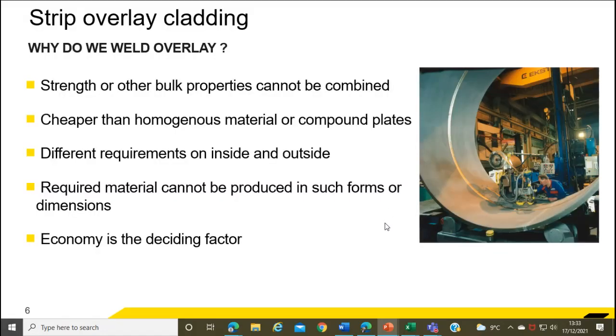So, making a start, introduction to weld overlay using strips. Why do people overlay in the first place? It's really because it would be too expensive to make a solid part or a whole item from the corrosion resistant material or the wear resistant material. It's very much cheaper to get the mechanical properties of carbon steel, high tensile, whatever, of a cheaper steel, and then coat the surfaces that need the protective coating. You can see the photograph on the right hand side. This is the inside of some kind of vessel, and the strip cladding has been put onto the inside. So you've got the mechanical strength from the carbon steel, and all the issues regarding fabrication are in carbon steel, so a little bit easier than stainlesses, for example. Plus, it's a lot cheaper. That's why people do it.